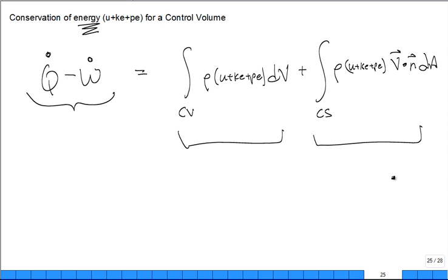That's the energy balance equation. What we do is this work term, if you take out the pushing the atmosphere back as it flows out, or being pushed in, when you bring that term over, guess what that U turns into? U plus PV, H, enthalpy. Enthalpy. Okay? But that's separating out the pushing in and pushing out boundary work terms for the fixed control volume.